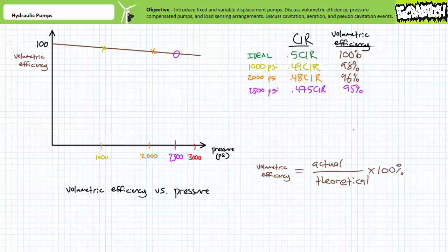Reduced speeds may be necessary for certain oils exhibiting different viscosity and lubricity characteristics. Speaking of fluid properties, note all performance curves must be standardized by using a liquid with a stated viscosity, temperature, and cleanliness standard. Pump manufacturers may provide additional performance curves for liquids with different characteristics.